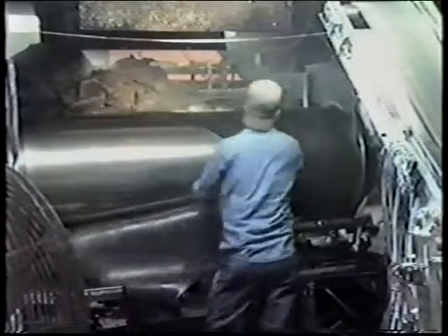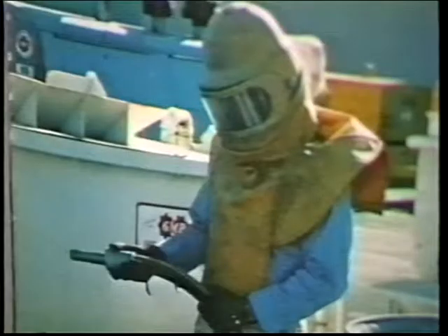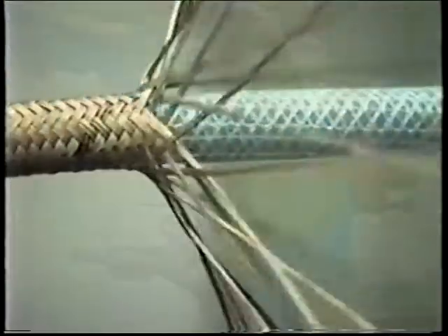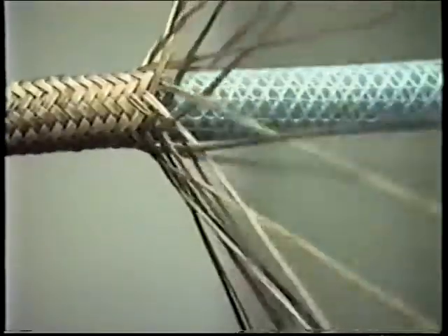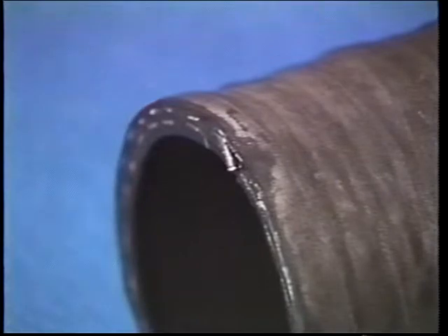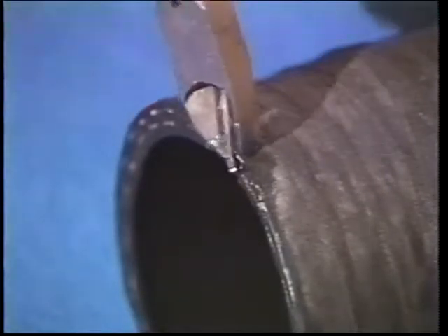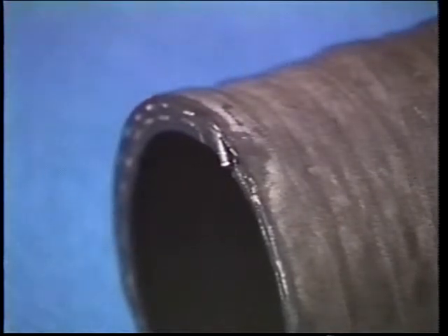Machine-wrapped construction offers a variety of tube and cover compounds. It is typically used for water and acid discharge hoses, as well as for sandblast hose. However, it is generally not capable of the higher working pressures available with horizontal braid construction. Suction applications of wrapped hose require the addition of a helical wire included in the reinforcement. This requires that they be hand-built on a mandrel.